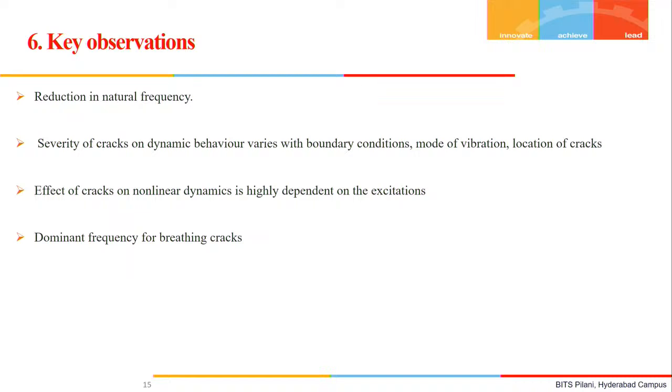Severity of the crack on the dynamic behavior varies with boundary conditions. With boundary conditions, if we talk about the clamped structure, if there are some points of contraflexure and the cracks are at those points, then there will be no effect of the cracks. If we talk about the second, third or higher mode of vibration, and there is a vibration node where the crack is located, we will not get any response from the crack, any effect of the crack on the response.